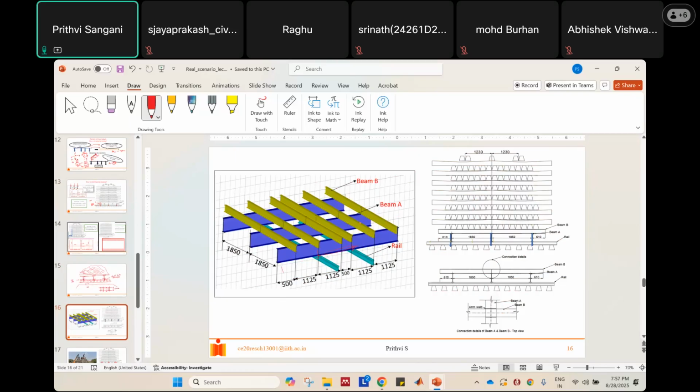Now what we need to do is when we place the load above these, you can see this is my railway track, and above the railway track I have beam A, and above beam A I have beam B. There are other beams which we have designed, and these are beam B. You can see these beam Bs have some spacings given over here. Now when we keep placing weight on top, both should give a reaction force of how much? 42.5. And also this part and this part should have 21.25 and 21.25 each. So that's why we have to design it as an overhang beam. You understand?